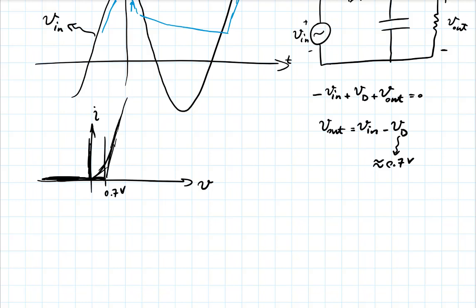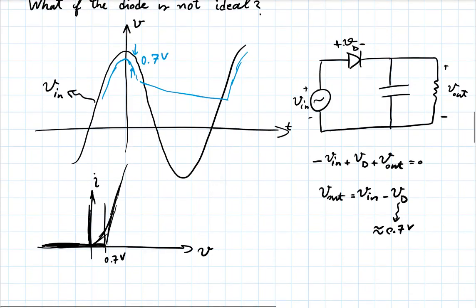And as you go through this cycle, the charging part of the curve, as the current changes, because the rate at which you're charging the capacitor changes, the voltage across the diode also changes. And so this blue curve, during that whole charging part, will be slightly shifted with respect to the black curve. And that would be a value somewhere around 0.6, 0.7. And it would be varying.